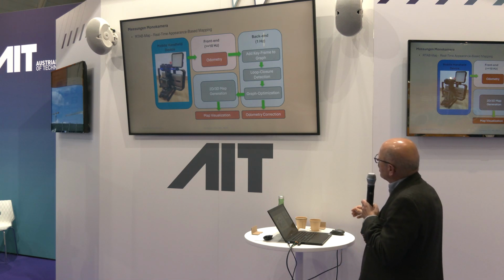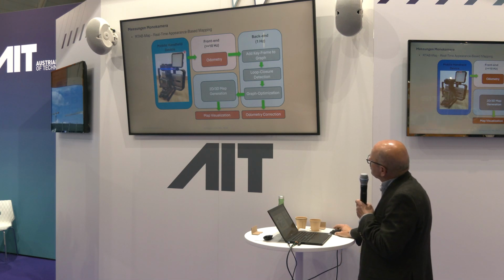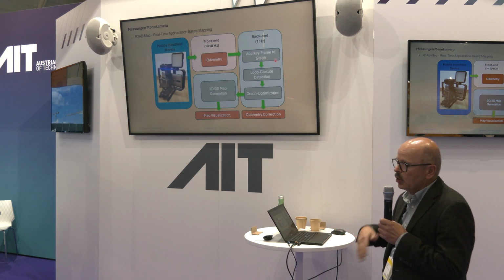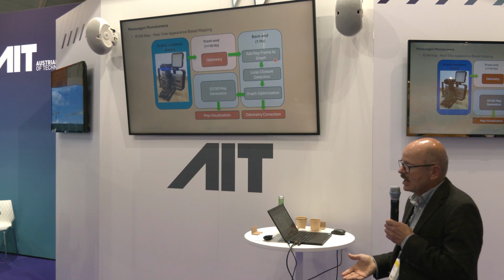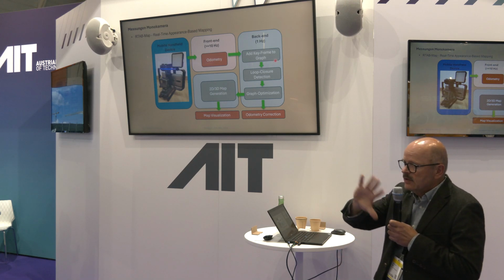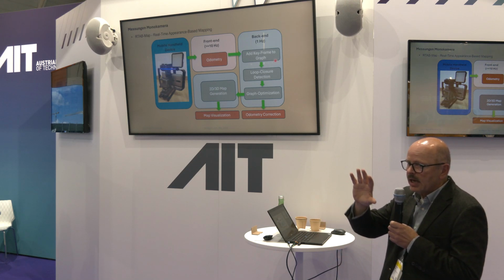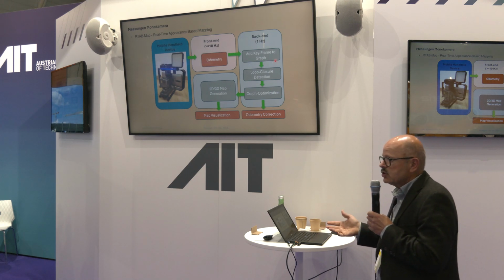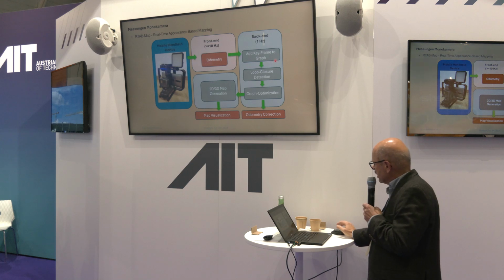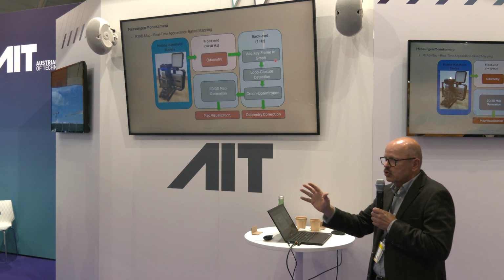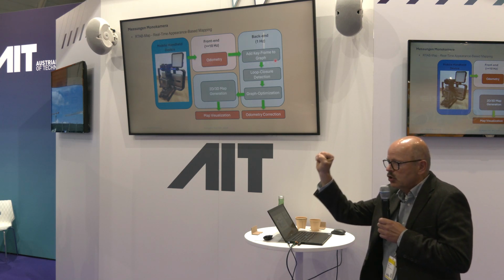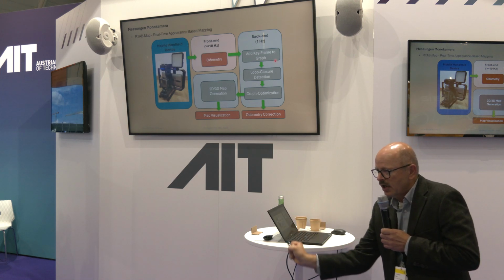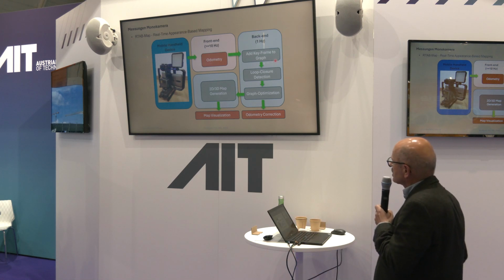After this we send this odometry data to the backend, which then operates once a second. It takes the keyframes from one frame to the other and combines different frames, and it tries to do loop closure detection to get from one image to the other, because by scanning you move the camera and have several different images.